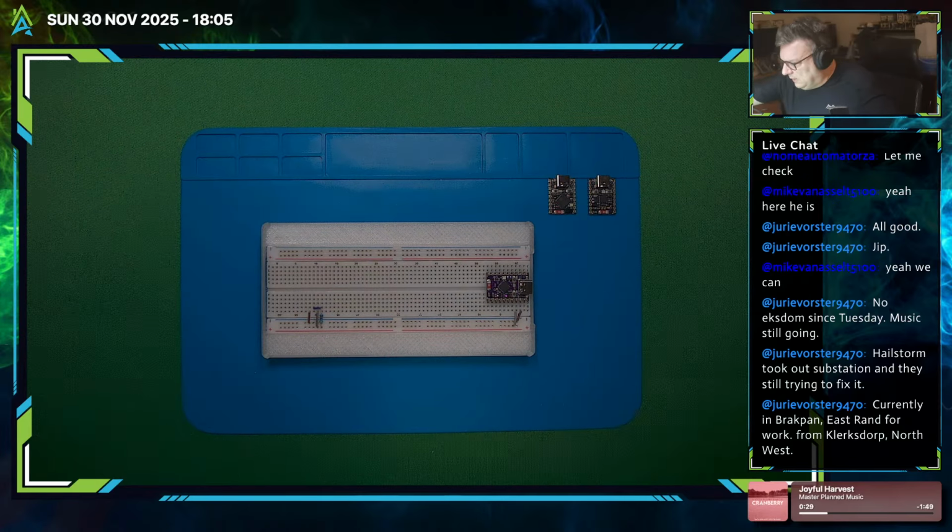Yeah, you can. The tip has some solder on it. It just helps to start the solder. And I just go and I just put it in here. You see how nice it is. As I say, it just helps with the solder afterwards.